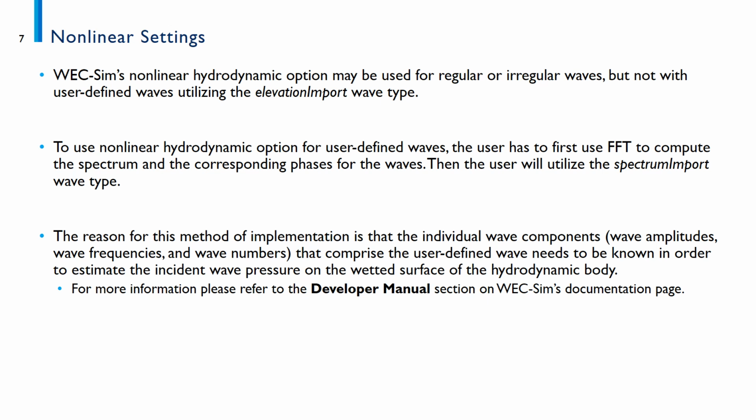The reason for this implementation is that the individual wave components, which is amplitude, frequency, and wave number, that comprise the user-defined wave need to be known in order to estimate the incident wave pressure on the wetted surface of the hydrodynamic body. Refer to the developer manual for more detailed documentation on WEC-Sim nonlinear hydrodynamics.